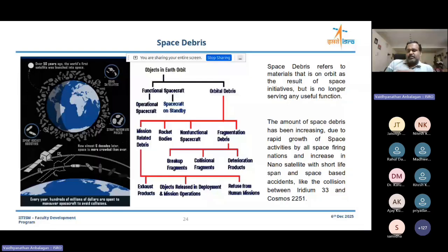So when this fuel is over, even if the satellite is drifting, we cannot fire and take it to the required orbit. And once it is not in the required orbit, it will not do the intended job. Say for example, if you have put a remote sensing satellite, and its lenses and cameras are designed to work at a particular altitude, and if it comes down, then the image quality will not be the same. So we say a satellite is live till the time we are able to housekeep that particular satellite.